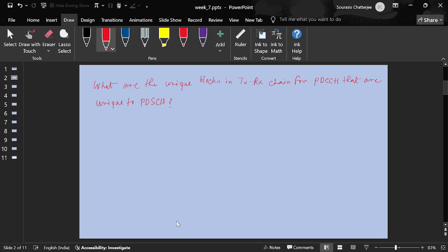Like CRC, if the PDCCH CRC matches its own RNTI, okay, that is the control, otherwise it is terminated as it is from another user. So before that interleaving, some CRC scrambling block should be there, right? Yes. And scrambling happens, as you mentioned, with some user specific information, you said C-RNTI, correct?